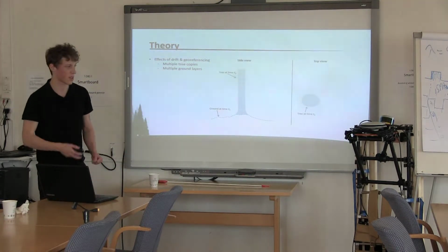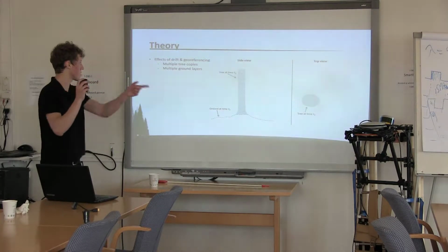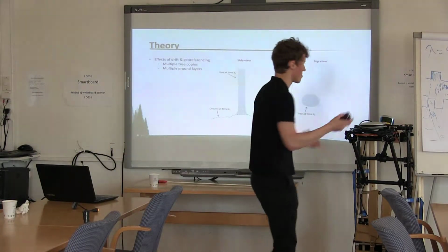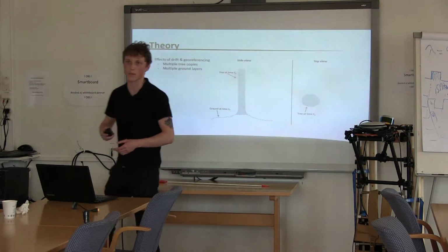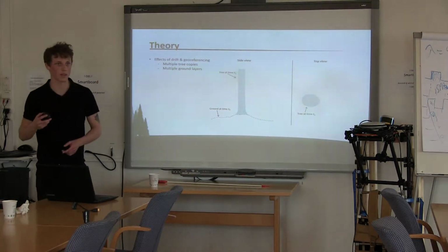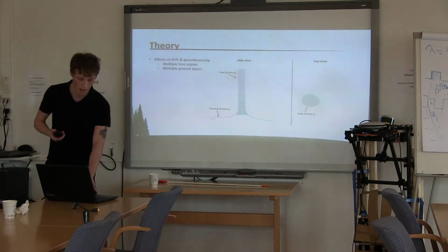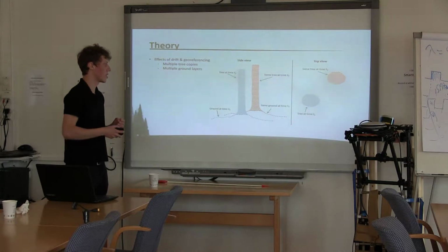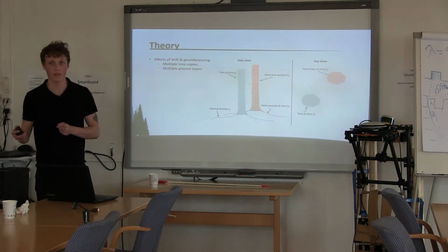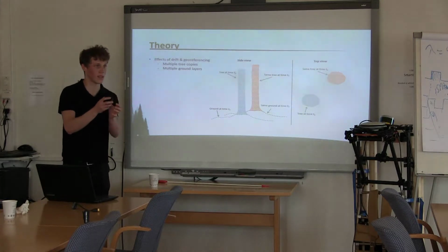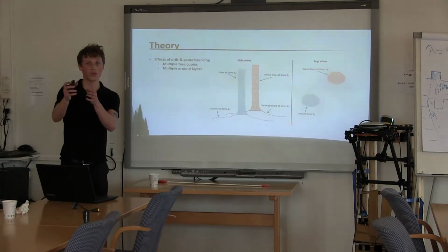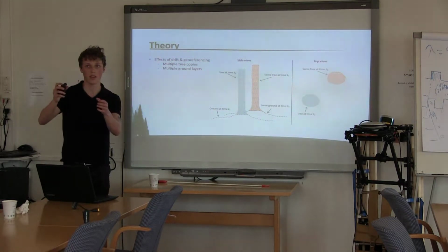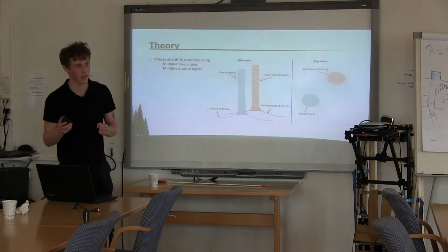And to illustrate this, let's say I'm scanning, I'm walking with that stuff, and I'm seeing this tree at time t1. And I'm walking, and then I'm coming back to maybe roughly the same position, and I see this tree again. The laser scanner sees this tree again, and the ground as well, at a later time, t2. Well, since we have another error at this time, we will see two trees, duplicates of each other, located at different locations in space due to this error.